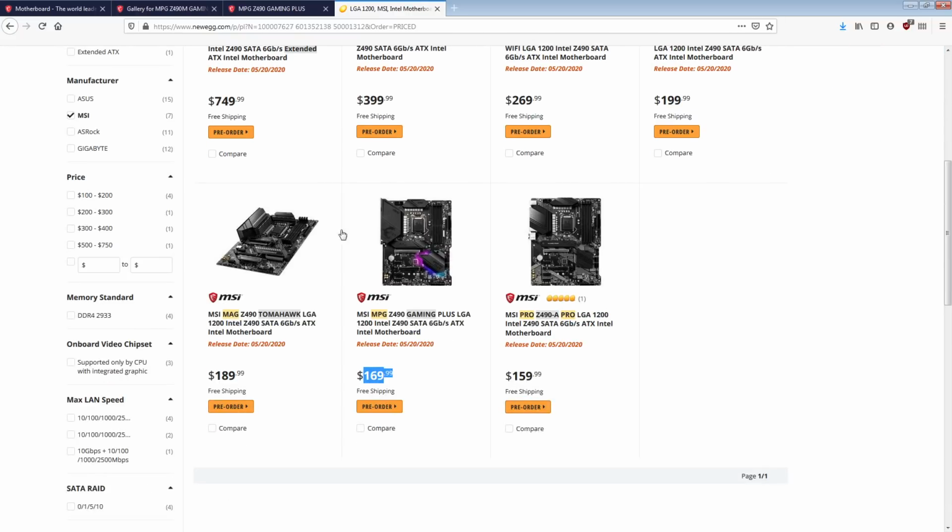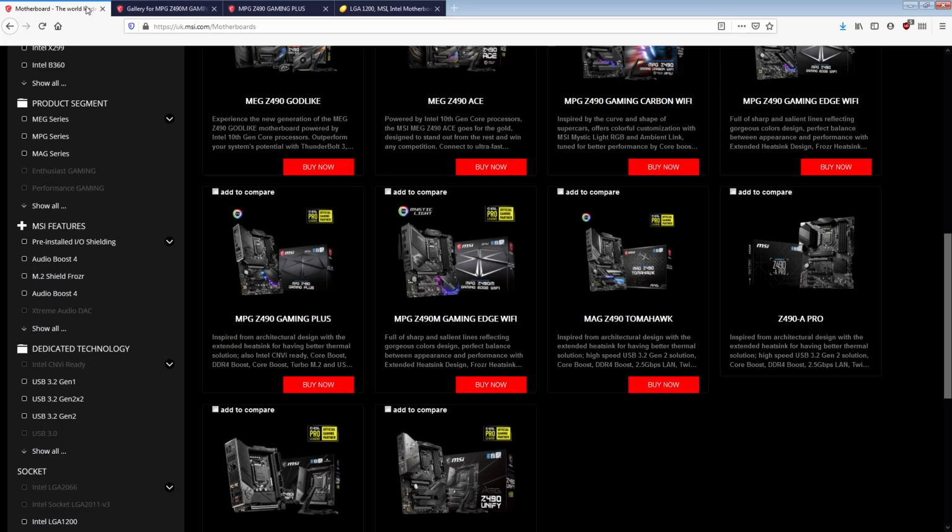The thing is, I'm not sure how that mATX board is going to compare, because Asus has a Z490 mATX board that uses actual 50 amp power stages, but they only have 8 of them. So I'm not sure how what MSI is doing here with the 6 massive phases works out against the 8, like, 4-phase, even larger 4-phase that Asus has. I'm not sure which one wins. This should have lower thermal density. This has more surface area. It's a bigger VRM, physically there's more area to it, so if the efficiency isn't too far off of what Asus is doing, then this probably would end up with better thermals.